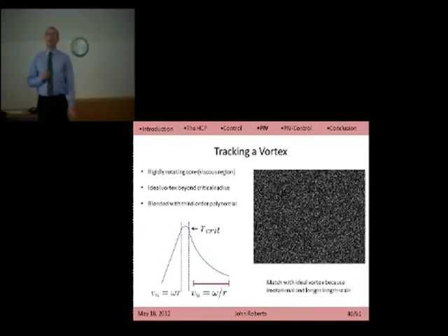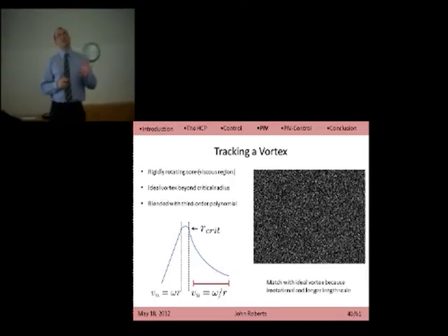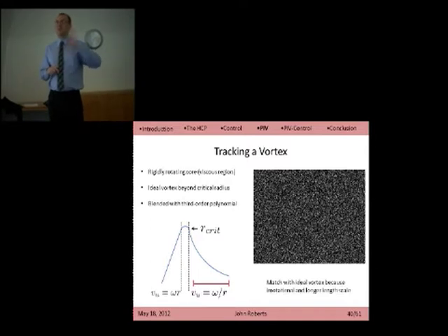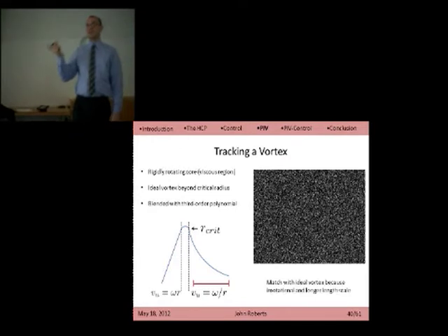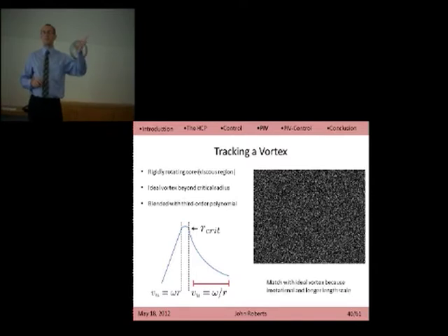So to find that vortex, we know the shape that we want. We want to find that spinny shape, but what does that shape really mean in a more detailed sense? Well, in fluid dynamics, there's a model of a vortex called a Rankine vortex, which has a rigidly rotating core that just spins around. That's where viscosity is dominant. Farther away, we have an irrotational vortex in a potential flow, and then you blend them together. What we want to do is track that farther-out irrotational vortex component. We want to look for the shape of an irrotational vortex in the flow.